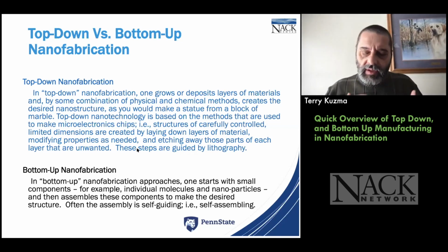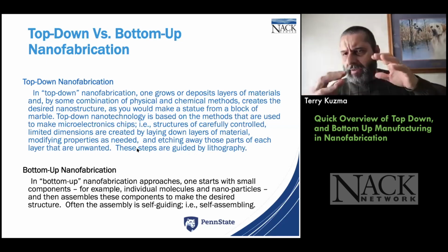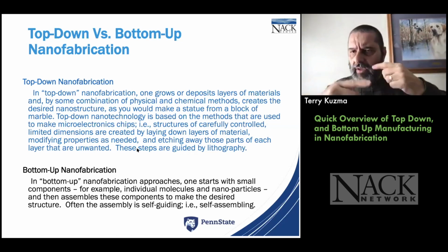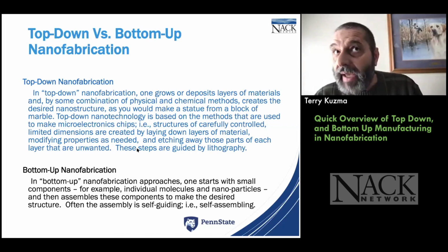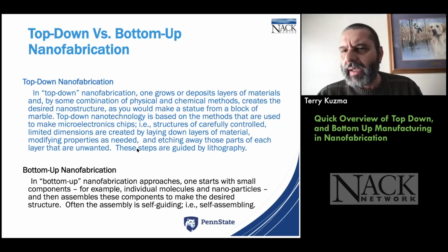And what we do is we take material and then we pattern it, usually deposit, etch, pattern, deposit, so we go through a cycle and it's repetitive. I think I mentioned, a microprocessor might take like 600 steps, and when you look at self-assembly, I don't think any of them are like a dozen.